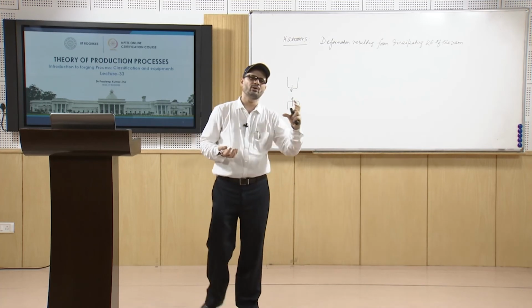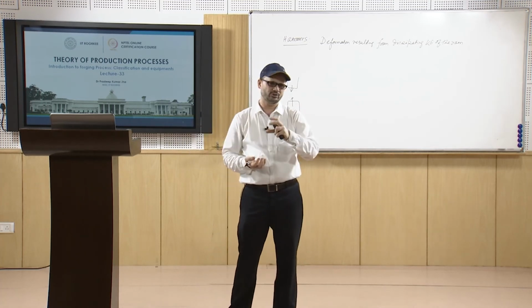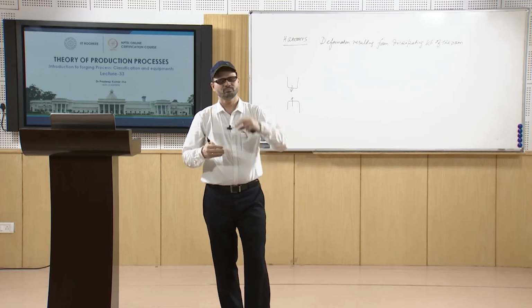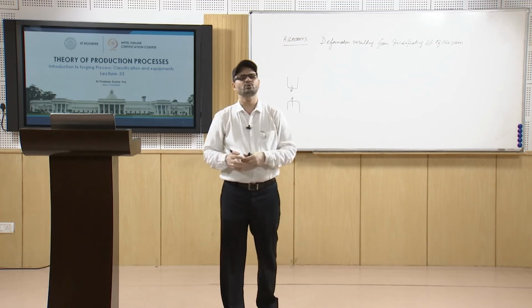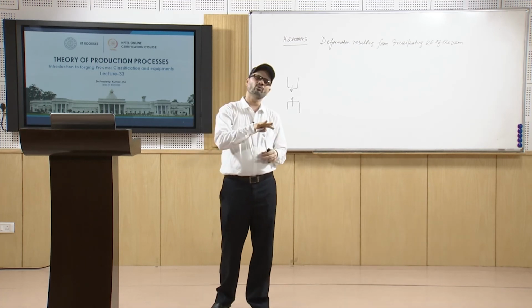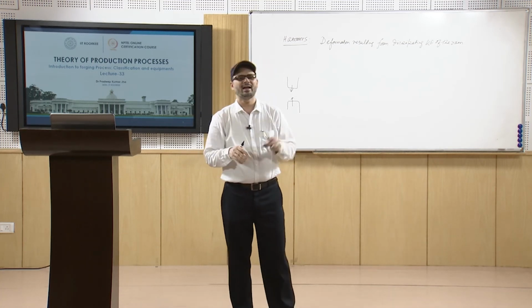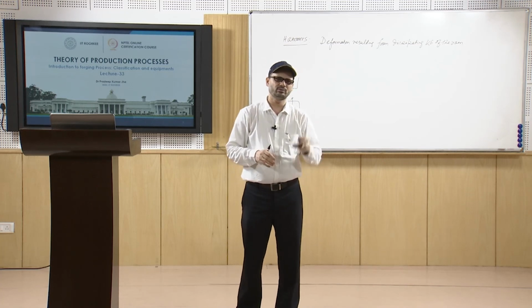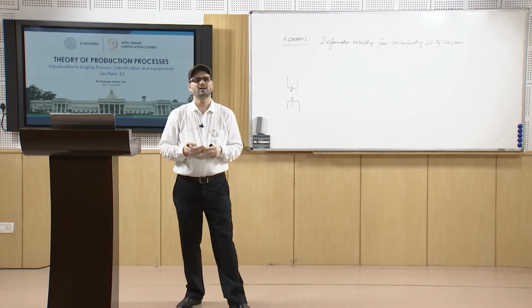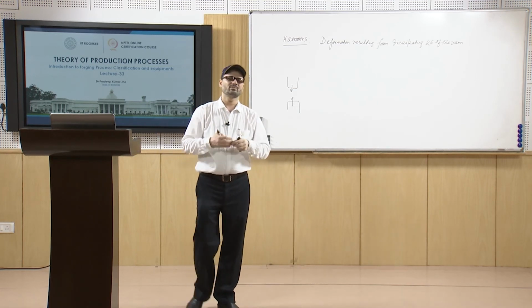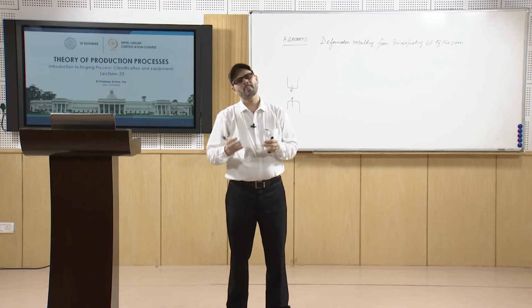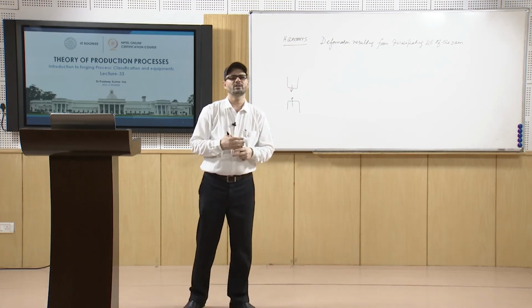But before that, you have to change the dimension to a proper size, and then you go for impression die forging, and the metal is put in between. Otherwise, sometimes the pressure requirement or the forging load requirement will be quite large. This way we do these forging processes.